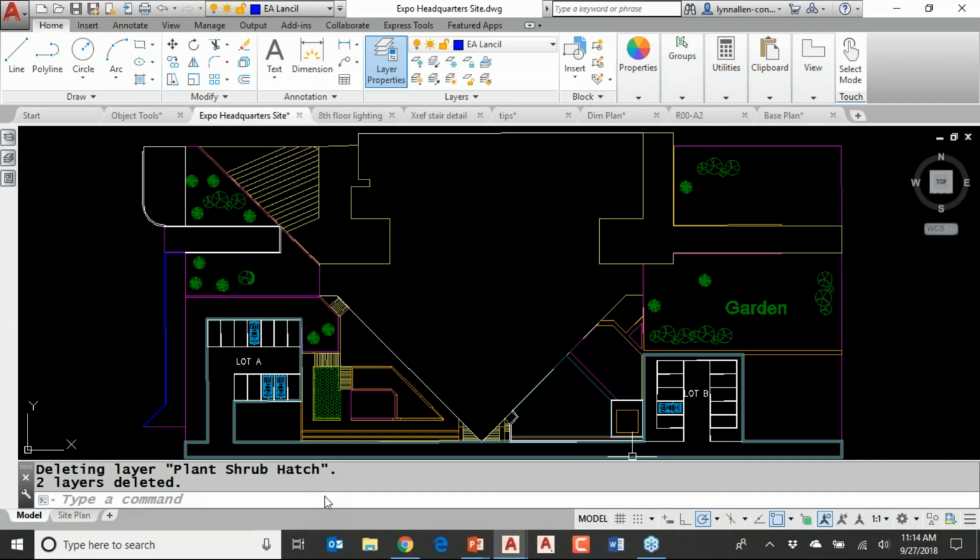All right. Can you undo it? Of course you can, but you need to be paying attention to what's going on, just so you know. So that's lay merge. Really comes in handy when you want to take objects from one layer, put them on a different layer, and get rid of the layers that the objects were previously on.